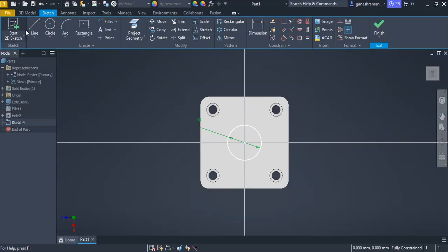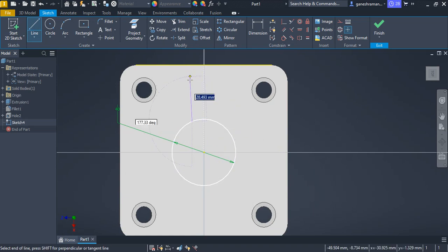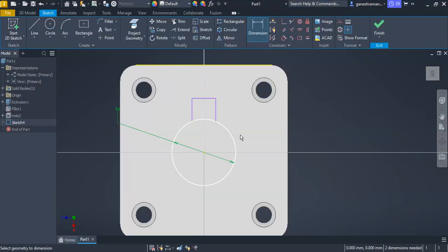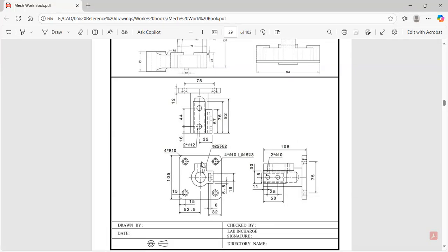Fine, and select the Center Line command again for construction purposes, at this point and this point. Make it construction and select the two lines again, like this, and make sure these two lines are symmetric about this line. Use the Symmetry relation on these two lines and the midline. So now it is okay. What about the length of this one? It equals this one, which is nothing but 30, right? So 30, enter. Now this length, how can I get this length from here to here? From this edge, which is not correct.